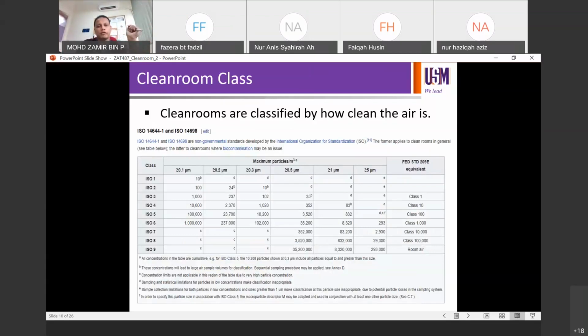So if you talk with a fab, usually you will talk about specifications. Specification is spec lah, macam SOP lah, standard operating procedures. So you will find perhaps on the HEPA or ULPA filters PM or preventive maintenance. You will probably find that the filters have to be replaced like semi-annually or annually or twice or biannually or in fact quarterly or monthly. So depending on the requirements of the products.